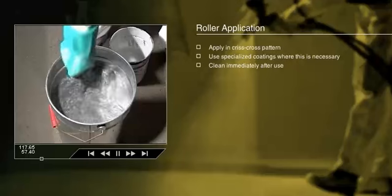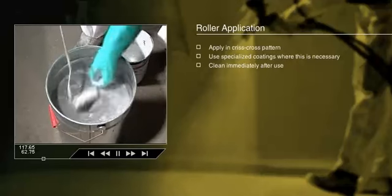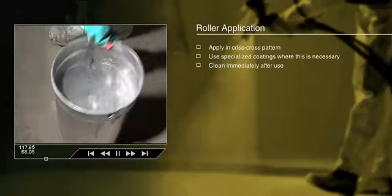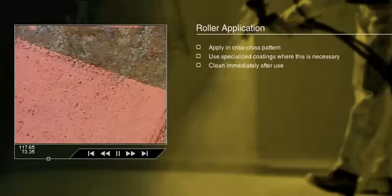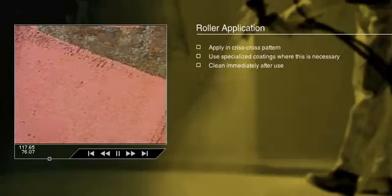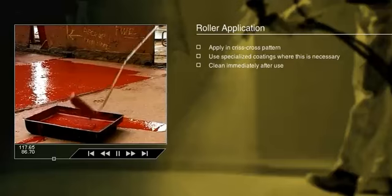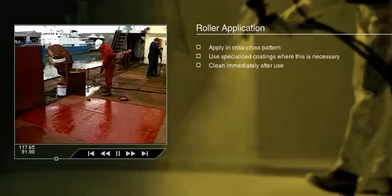Rollers must always be cleaned immediately after use. Problems with the use of rollers generally arise from carelessness with handling technique and maintenance of equipment. Rollers are not effective in forcing paint into pitted areas or displacing residual traces of loose dust and dirt from the surface. There is also a tendency for operators to apply a heavy coat at the beginning of a patch, thinning out to an inadequate thickness before a roller is recharged with paint.